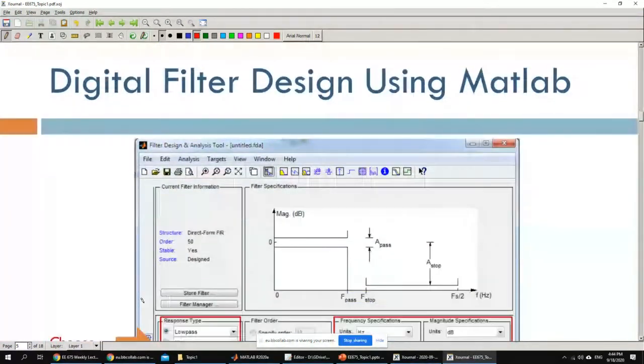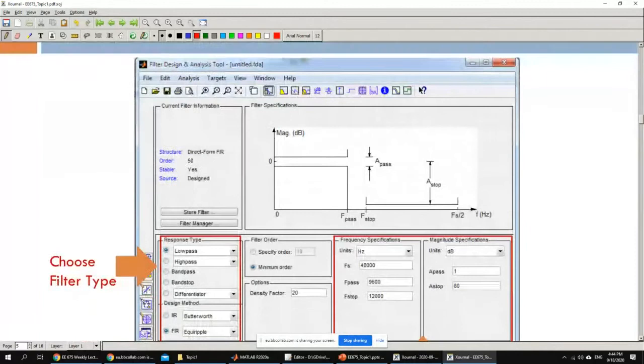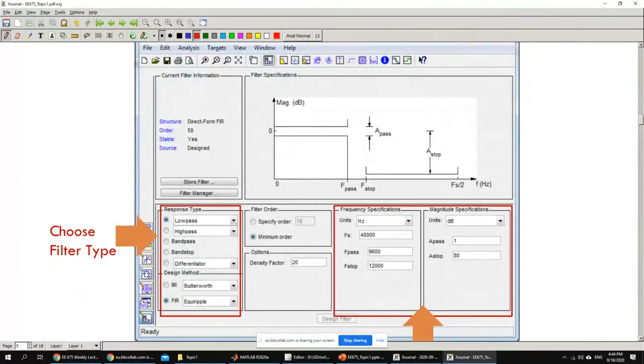For the filter design, what we did was to use a filter designer, as you saw before. Basically, you have to determine which type of filter. So if we are going to do baseline wander, then you're going to choose this. And you have to put the frequency as 360 because this is the sampling frequency of the data that we have, and then put here the f-pass and f-stop. These are these 2 points.